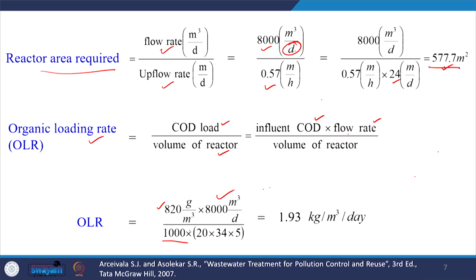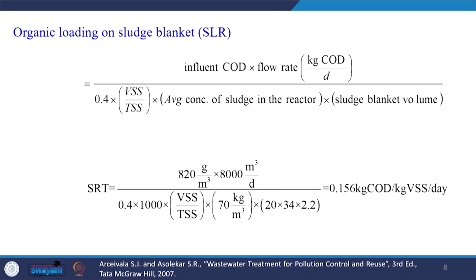So, if we divide by the height into this area, that will also give the reactor volume, and then we can get 1.93 kg per meter cube per day. So, this is the total reactor OLR which is required.